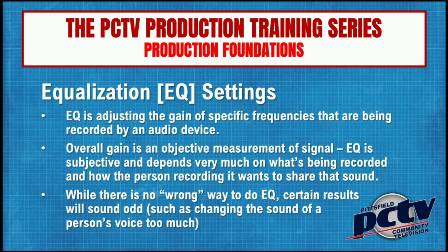Finally, when you're messing with your audio elements at the final step before it gets recorded, you've adjusted your gain, you've made sure it's not overloading. Now you can play with the equalization or EQ settings. EQ settings adjust the range of frequencies that is recorded by a piece of audio.